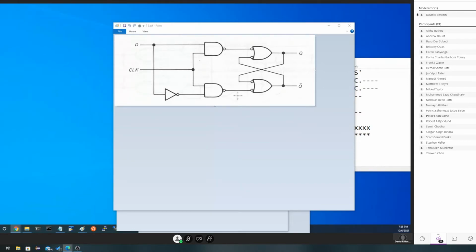And we'll explain, if I forget to explain what the word latch actually means, I'll do that shortly. But this happens to be level clocked. By level clocked, it means the entire time the clock is high, we're basically gating. Remember how we said an AND gate could have one of its signals trigger whether you could block data or not? This is exactly an example of that. When the clock is high, that's the only time these gates can have an output. If it's low, you can never get the condition on an AND that would cause it to make one of the varying values. So this turns out to be useful as a D latch.